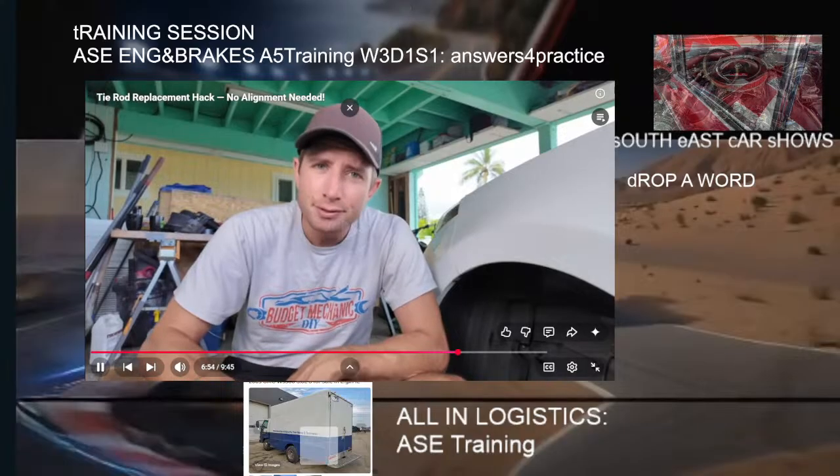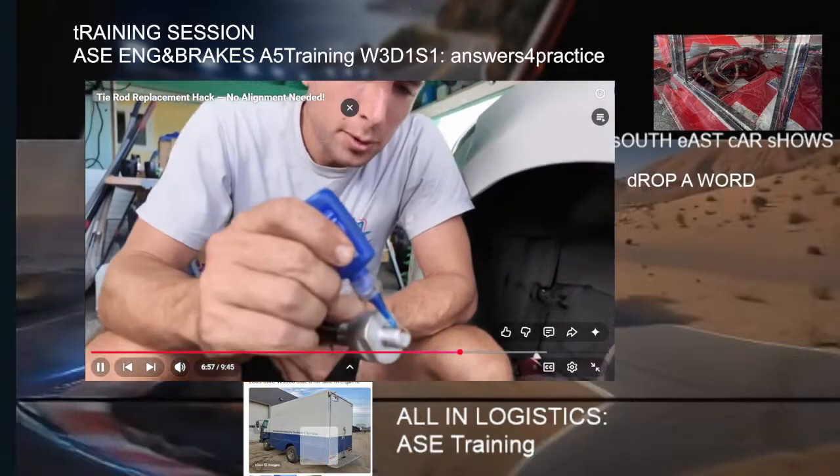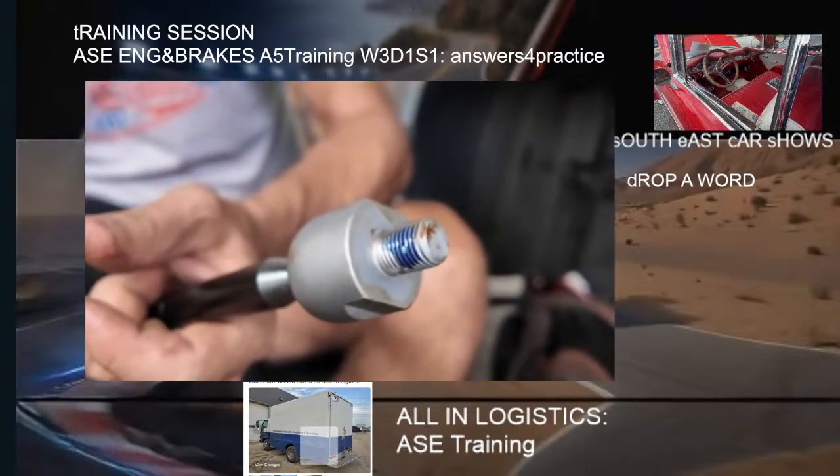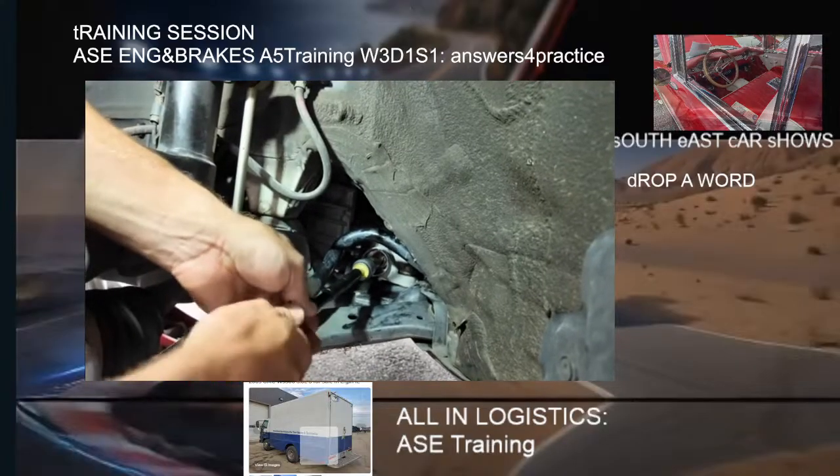Shoot, let's do it. One last thing before I put it in, I'm gonna put a little blue Loctite on these threads. Really don't want that thing coming off, that would be dangerous. Yeah, you're right about that.